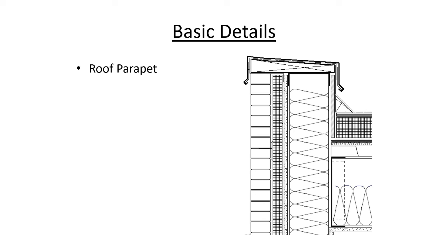Over the top is coping, and what is important from an energy engineering standpoint is that the air barrier be continuous without breaks, coming from the roof up behind the back side of the wall, over the top of the steel framing, and then down the face of the gyp sheathing. This is done using standard either peel and stick type air barriers or the liquid applied type.